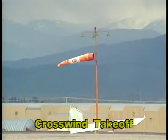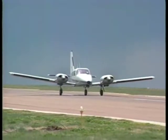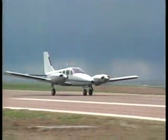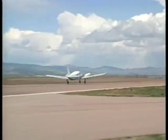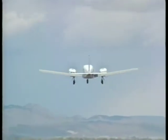Let's briefly look at a crosswind takeoff. The procedures are essentially the same as for a single-engine aircraft. You'll use the ailerons to prevent drift and the rudder to maintain directional control. As soon as you lift off, establish a drift correction to stay on the runway centerline.